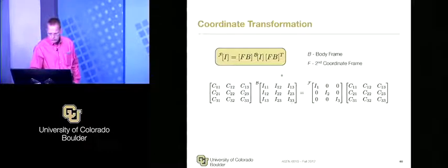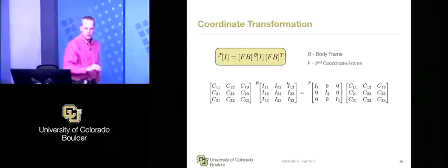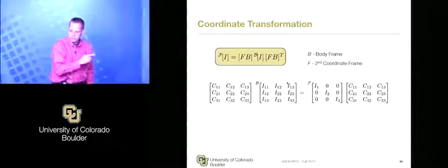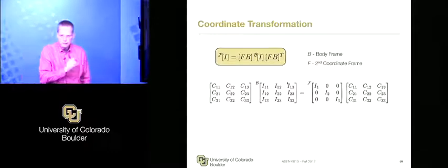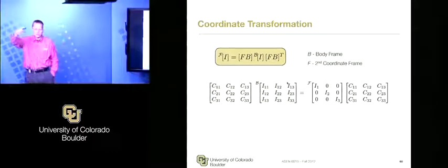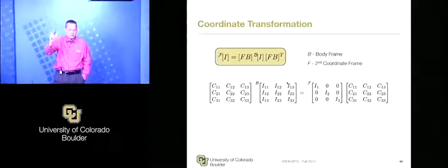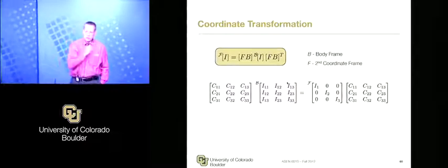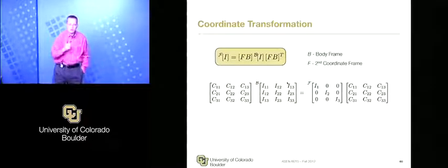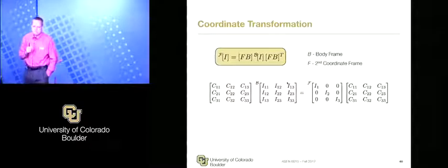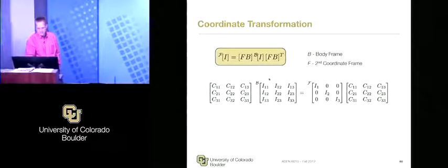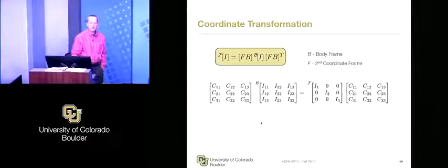If you have originally a 3x3 fully populated inertia tensor, which, by the way, is this thing symmetric or not symmetric? It's symmetric. If you go back and look at the definition, the off-diagonal terms are exactly the same. It's y squared plus z squared, y squared plus z squared. It's symmetric. Can somebody tell me if this thing is positive definite? Why, Kyle? It's a diagonal matrix, and all the values are positive. Well, in this form, yeah. True. And it's easy to prove it's positive definite.